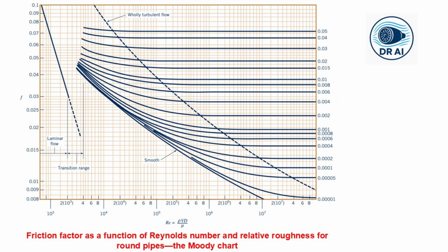The friction factor f decreases with increasing Reynolds number, following what's called the smooth pipe law. But for rough pipes, as Reynolds number increases, the curves eventually flatten out and become horizontal. This is the completely turbulent, or wholly turbulent, regime. In this regime, f is a function of epsilon over D only and is independent of Reynolds number.